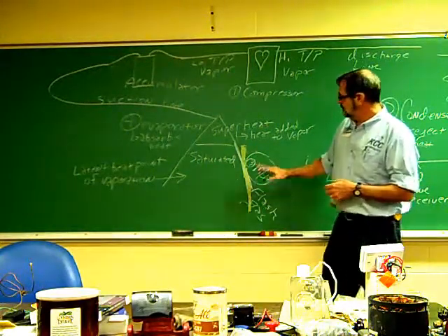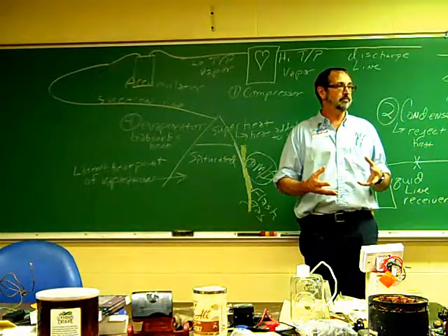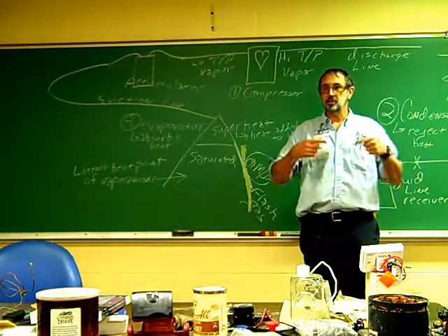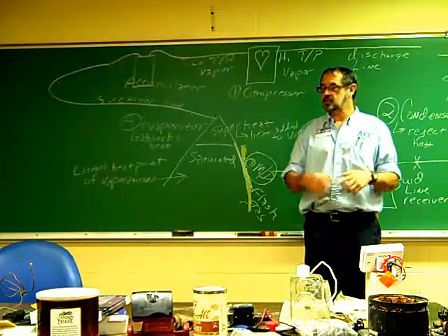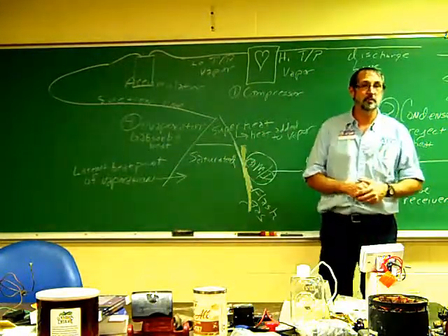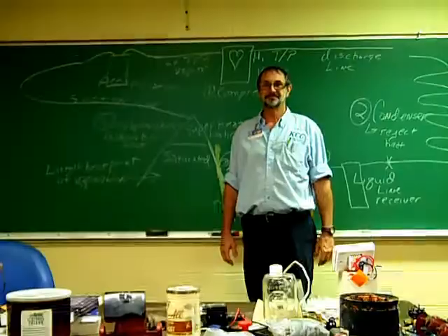So we have our metering device, engineered restriction in the flow of refrigerant. It helps to cause a low pressure, low temperature condition inside the next major component. Let's go there next.